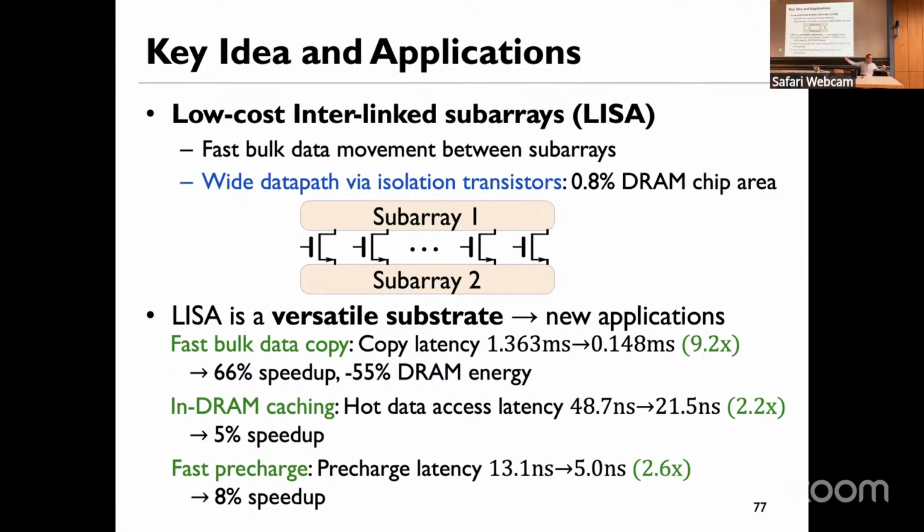And there are 2 issues over there. One is latency is long. The other is you may not have the signal integrity, because essentially, you have a very long, thin bit line, and you may not be able to reliably transmit everything, even if you wait forever. You see what I mean? Because it's not designed, at least currently, for that purpose.